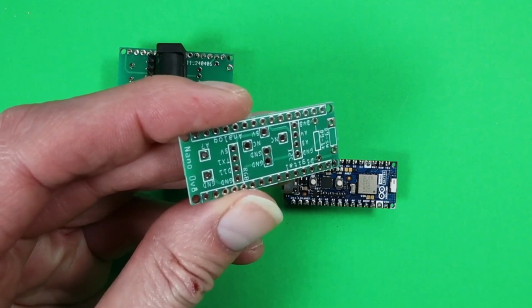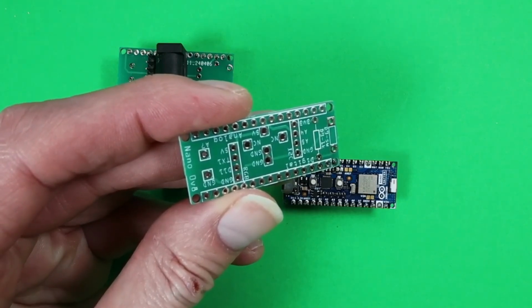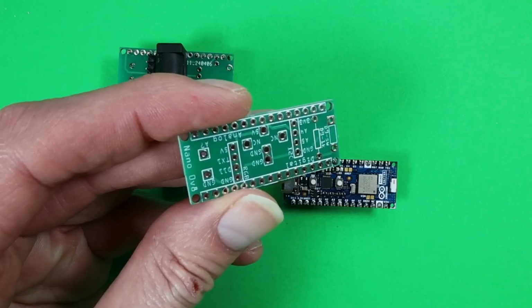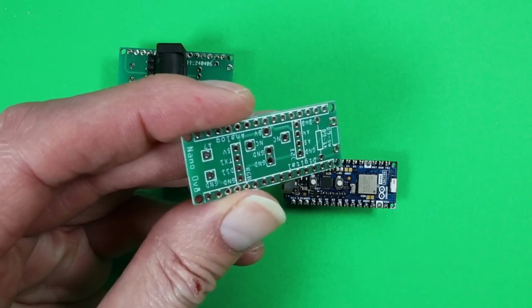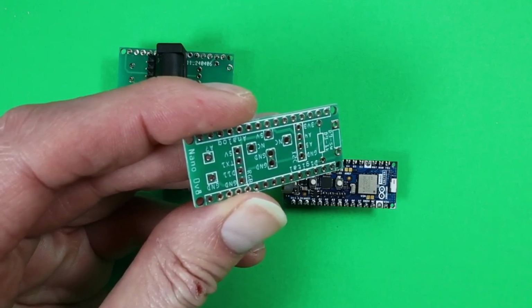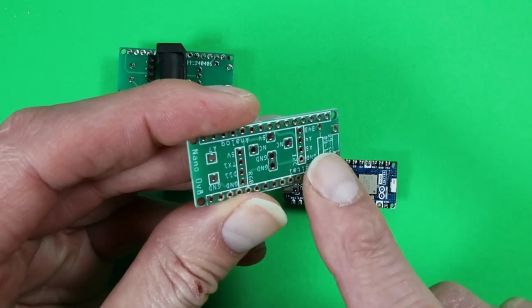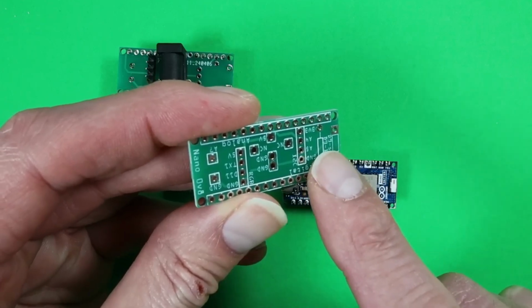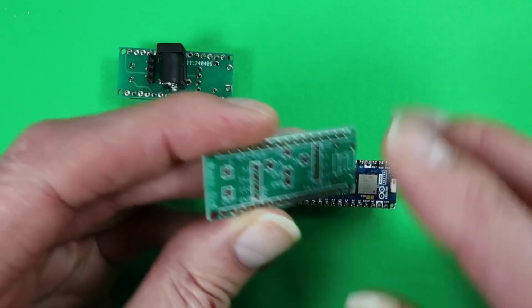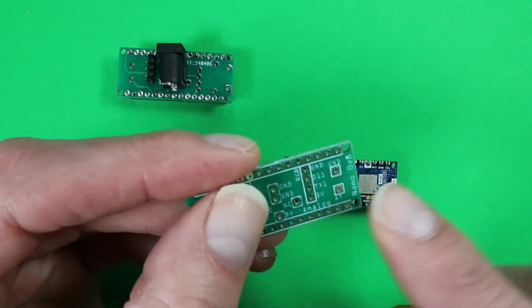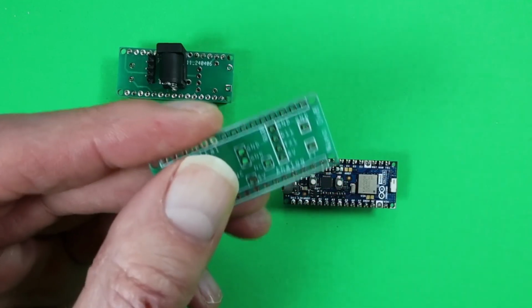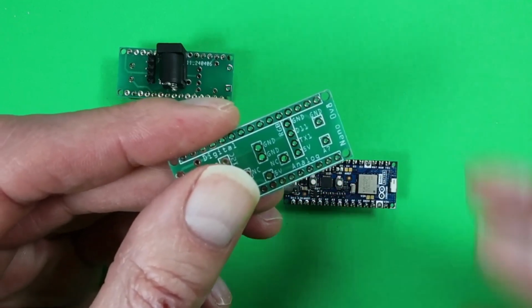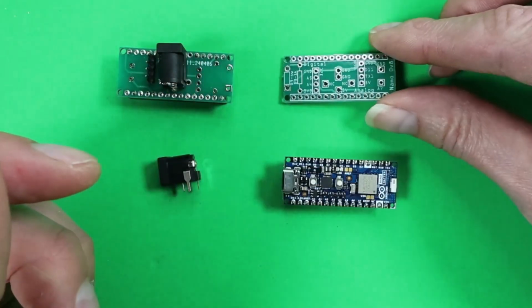Note, there are no pull-up resistors here for I2C. Lots of breakout boards have their own resistors, and if not, you'll need to add some. There are also holes to mount a button and a resistor if you want an extra input. Finally, there are holes I added for another GPIO and ground. These are intended to mount a small piezo buzzer, but you could make use of them however you want.